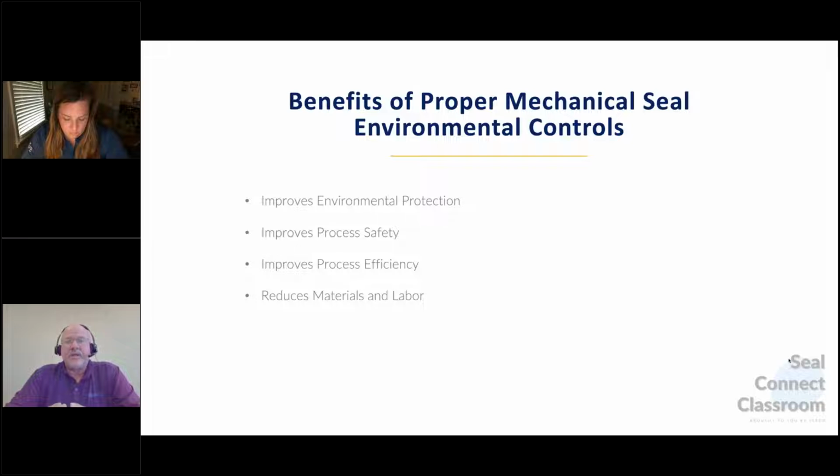And also creating that proper environment for the seal to live and to operate and be efficient and get good longevity out of it reduces replacement cost, material and labor cost to replace that seal. Most people, when they change a mechanical seal, change a whole rotating assembly for a pump or the piece of equipment. They have new bearings, they start all over again. So it's not just the cost of the seal involved in it, it's the cost of the actual piece of rotating equipment that you have to take into consideration when you do that.